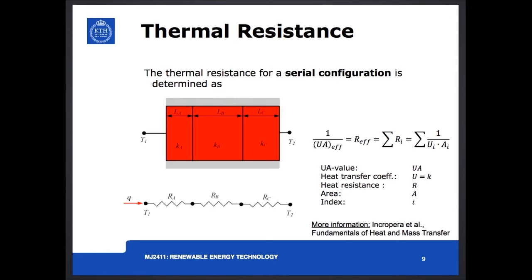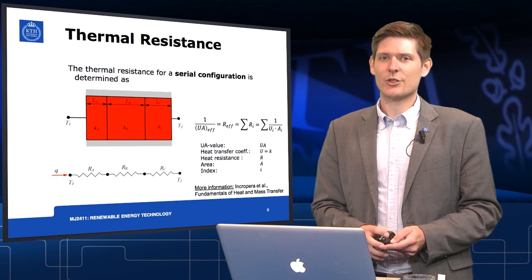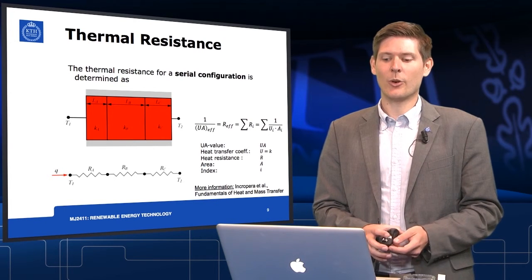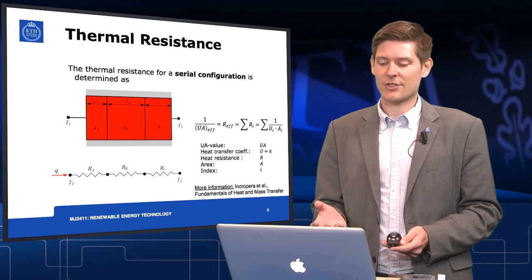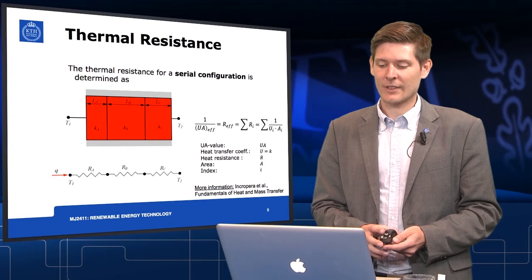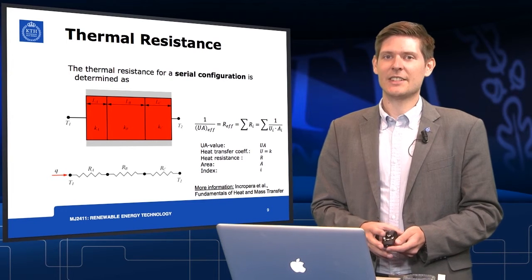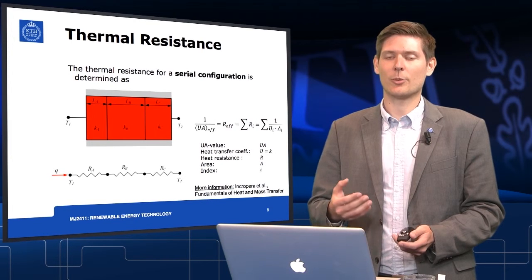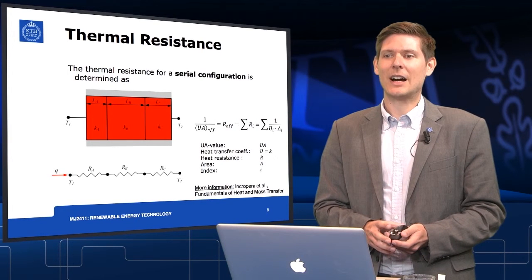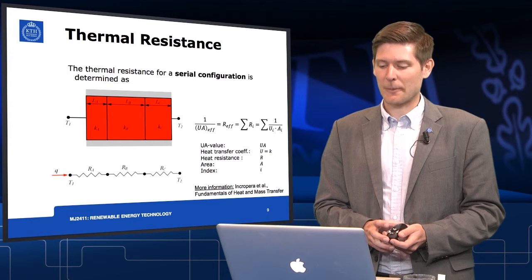To calculate now the useful heat and the efficiency of the power system of the solar collector, we can just use the equation which we have shown before and calculate the usable heat, Q_us, with the equation shown here. The efficiency, as in any system, can be calculated as the useful heat or the useful power divided by the power available at the solar collector.